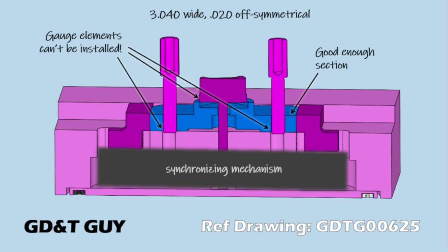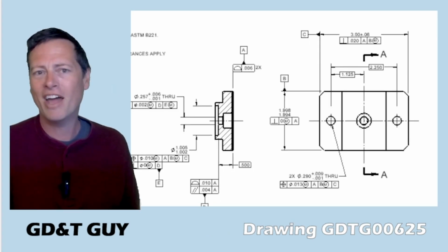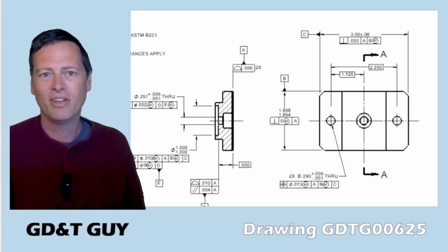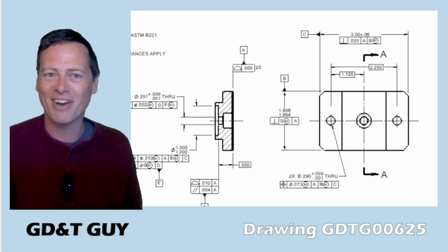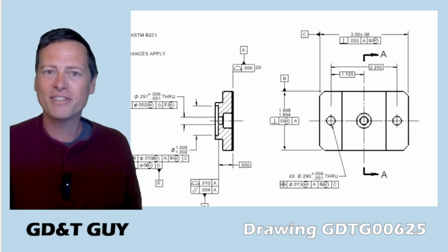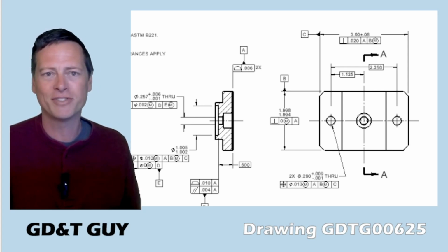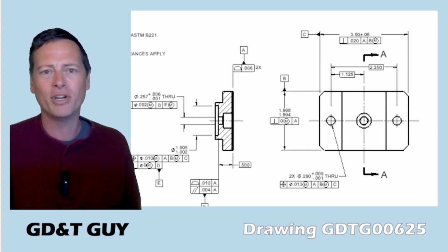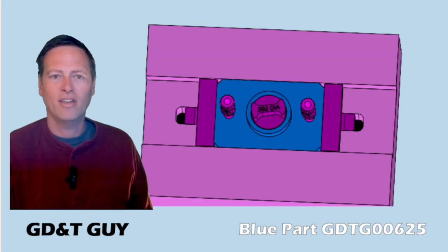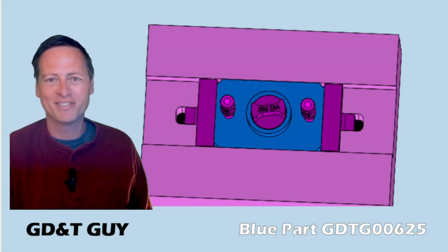But maybe that's what you're trying to control. It could be that it's important to you that the part be more than just visibly symmetric. But the way I'm looking at it, that's not what's important. On a lot of the work I've done, if it's pretty, it's a little suspect, right? So yeah, I don't think this is a very good functional datum reference because it prioritizes that symmetry over what I'll say are the real requirements of the part. And here we go again with my little grievances.